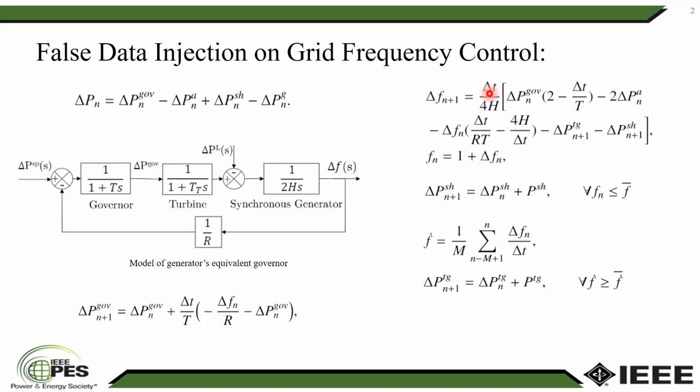These measurements go to the control center, and then the control center sends wrong commands to the governors, and this change in the governor set points can change the power output of the synchronous generators. The whole story happens like this. This change in the governor can make a load generation imbalance in the power system, and this imbalance can create some false relay operations in the power system.